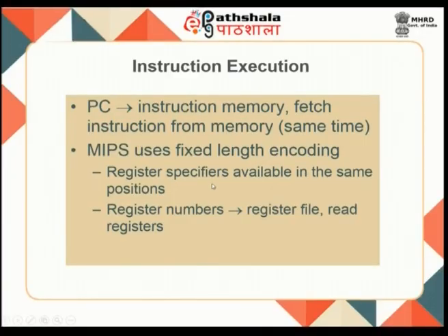Now, because of this fixed length encoding and the registers being available in the same position, as the decoding of the instruction takes place, you can also use the register specifiers, which are indicated in the register numbers, and go ahead and read the registers from the register file.